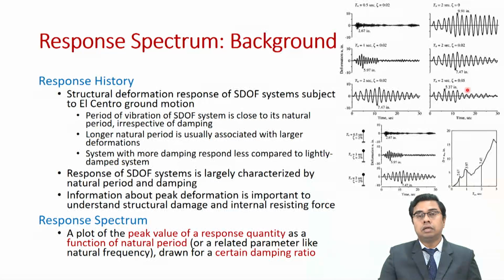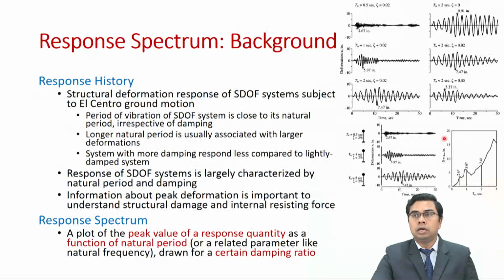Another observation is that the peak deformation, the information about peak deformation, is very important because it defines the likelihood of structural damage and what would be the internal resisting force, as we will see later. Therefore, we need to understand the peak value, and so we need to plot the peak value of any response quantity.